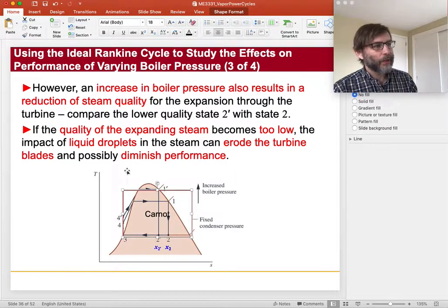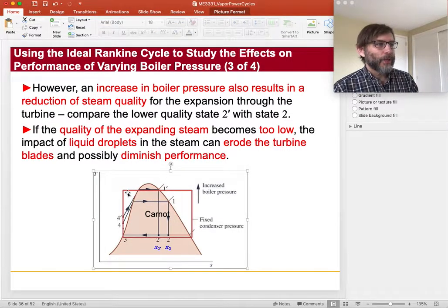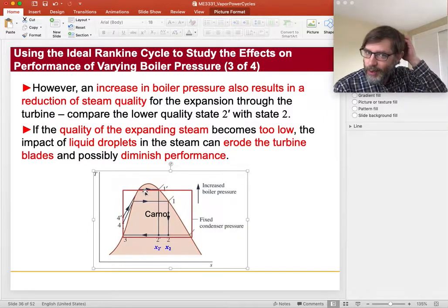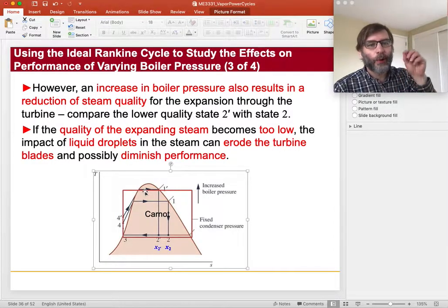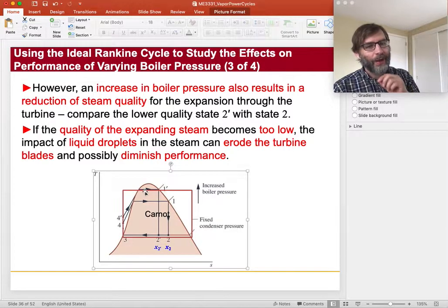The problem is that there's no practical way. You see the blank between 4' and 4 double prime here, and this top piece, and then this whole area. So there's going to be some area where you're not going to have the heat. So it's less efficient. What I'm saying is that the Carnot cycle is more efficient than a Rankine cycle over the same pressure ratio.